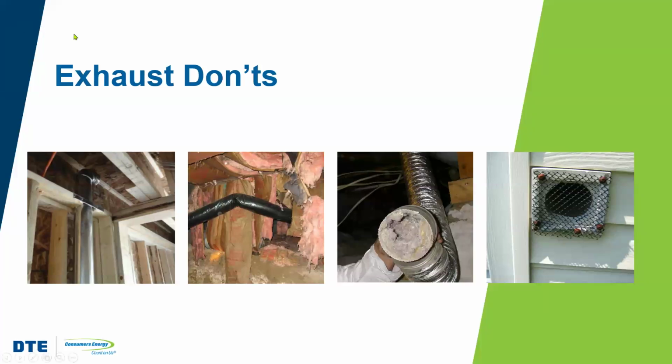So we've got some things that are wrong here in these pictures. And so here we've got a closed dryer that's venting here. We've got an elbow here, and then it doesn't actually terminate outside. So we definitely don't want to do something like that. We definitely don't want to terminate into a crawl space or anything where we can potentially create problems with additional moisture, right?